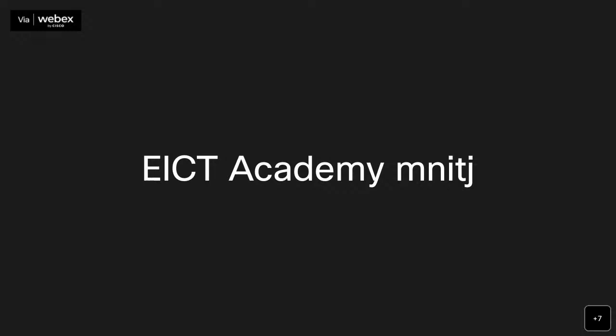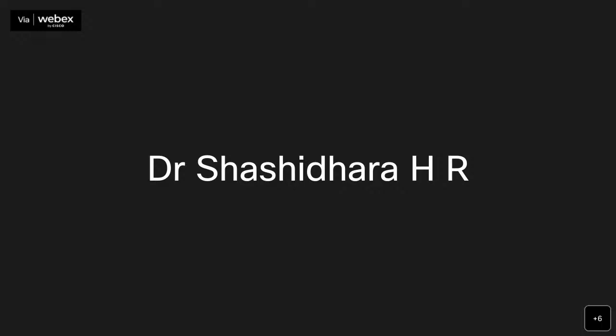Yeah, there are some limitations. In EDA Playground, what you are doing is only simulation modeling. It can't be synthesized; some of the constructs cannot be synthesized. Once you go to the Vivado tool, the synthesizable constructs should be used. If you are targeting only the simulator in Vivado, then the constructs map directly to the simulator.